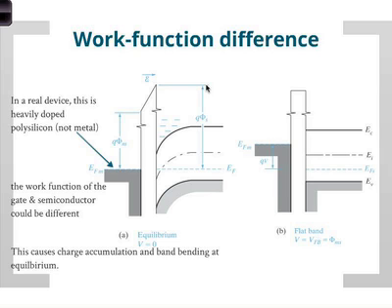Typically, by the way, in an actual device, this is really not a metal. In almost all the conventional integrated circuit MOSFETs, the gate is made out of very heavily doped polysilicon. Polysilicon means polycrystalline silicon. So remember, polycrystalline means you have lots of crystal domains. So it's no longer single crystal. It doesn't need to be because you're not using this with the energy bands. What you're interested in is that you heavily dope it to make it look like a metal.